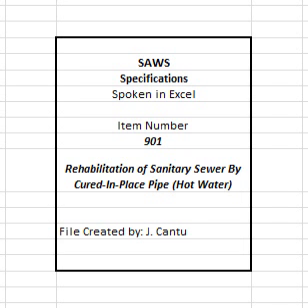3. Public notification. A. The contractor shall maintain service usage throughout the duration of the project. In the event that a service will be out of service, the maximum amount of time of no service shall be 8 hours for any property served by the sewer. A public notification program shall be implemented, and shall as a minimum, require the contractor to be responsible for contacting each home or business connected to the sanitary sewer, informing them of the work to be conducted, when the sewer will be offline, and any alternative method of service that may be provided.